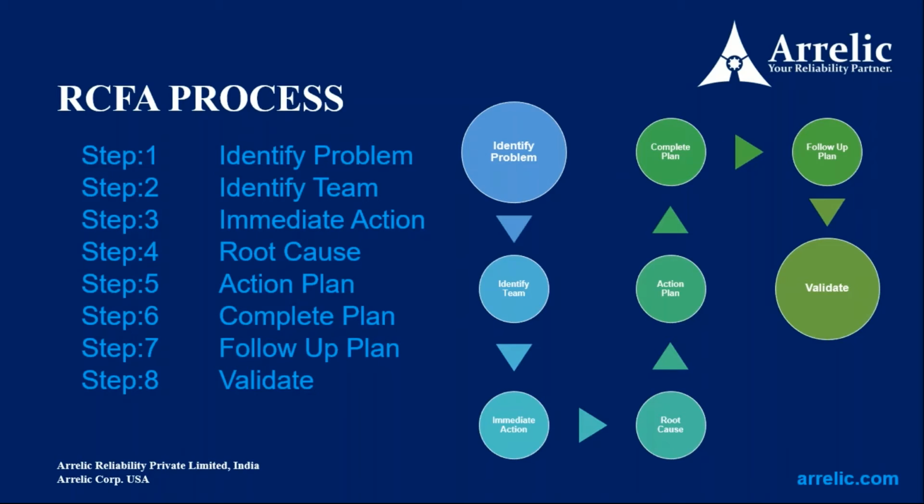RCFA process: identify problem, identify team, take immediate action, find the root cause, establish action plan. Step 6, complete the plan. Step 7, follow up the plan. And step 8, validate. Again, following the process one step to the next.